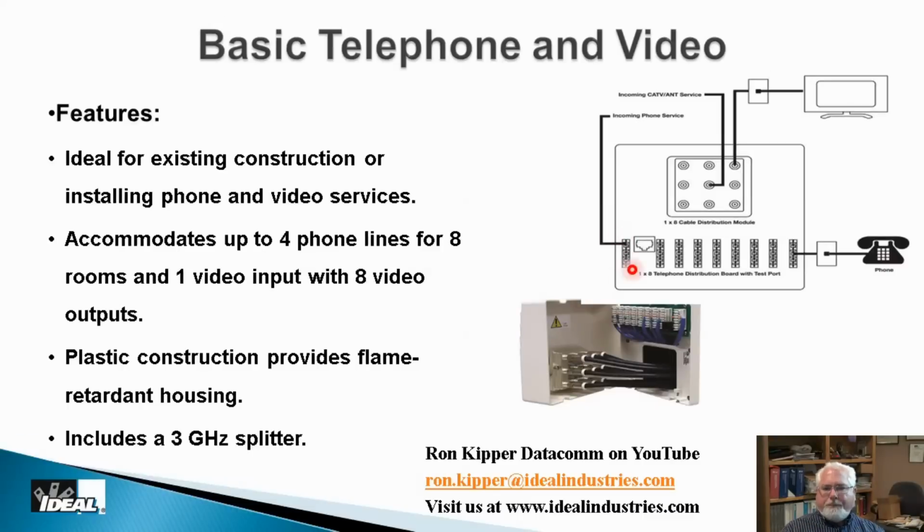And on that board, one of them will say from demarcation or incoming line or something like that. And I would bring that cable from that demarc on the outside of the home, that NID, and run it into here and terminate it on that telephone board, again, utilizing a punch-down tool. And, watching my other videos on how to use punch-down tools and how to make these connections up, you'll find them in like my smart home series and things like that. And bringing up to 4 incoming phone lines is what they're designed to handle, okay? And this board splices all these other connections together.